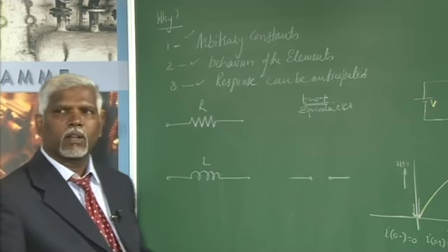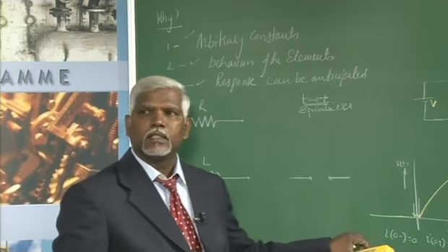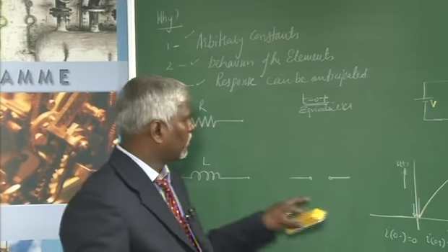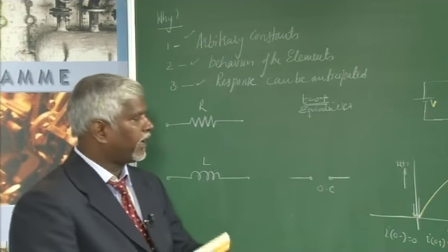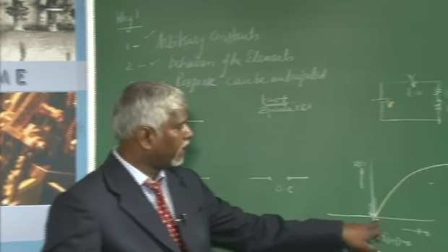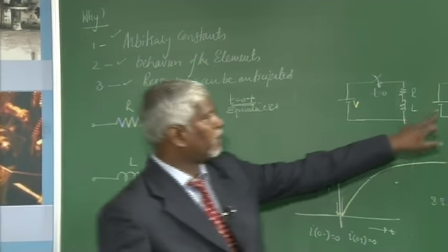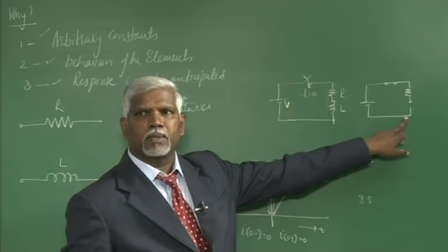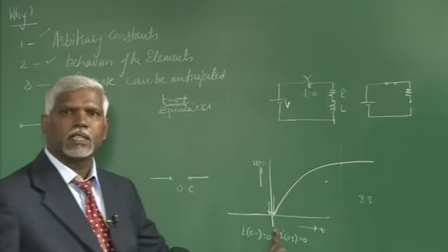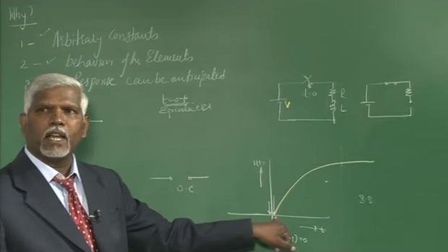This particular table that I am going to put will help you in understanding the circuits over the next 6 classes. So, this acts as an open circuit. Just because it does not allow any sudden change, the current immediately after closing the switch is also 0. So, effectively I need to represent the inductor as an open circuit to substantiate that it does not allow any sudden change in current. Therefore, the current remains at 0 immediately after closing the switch.